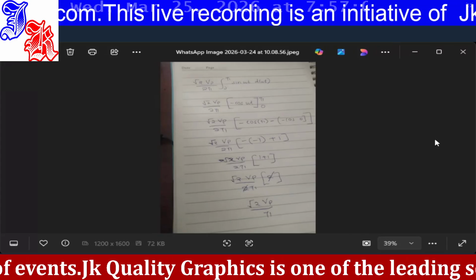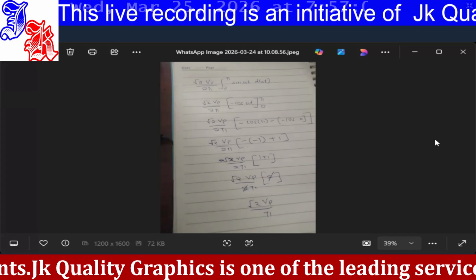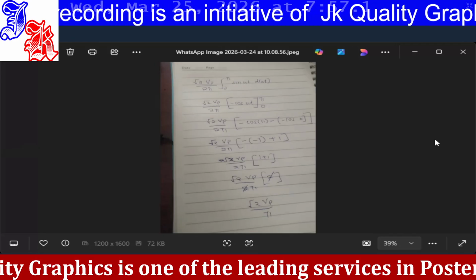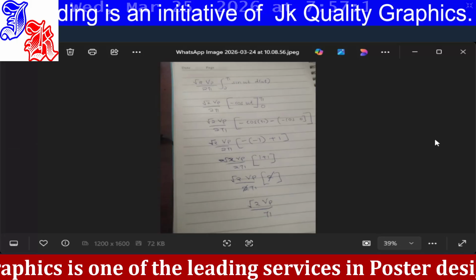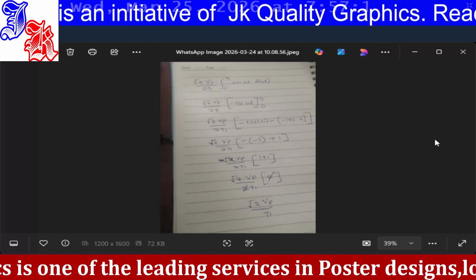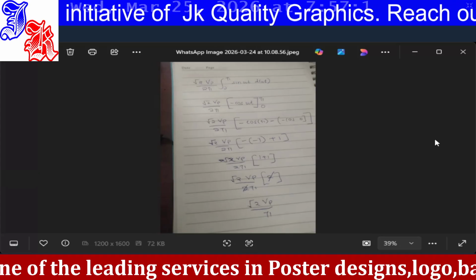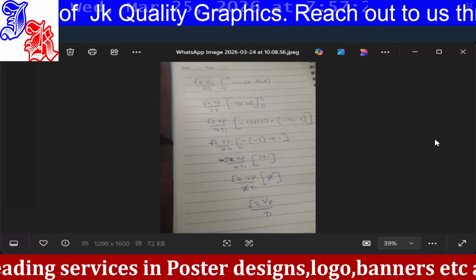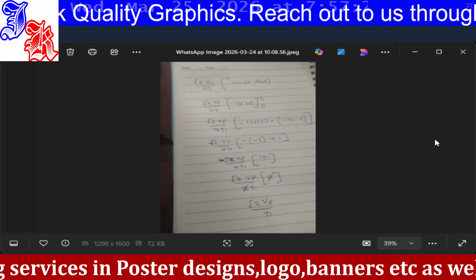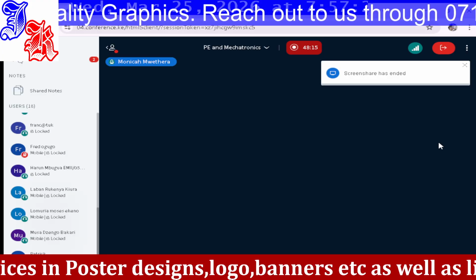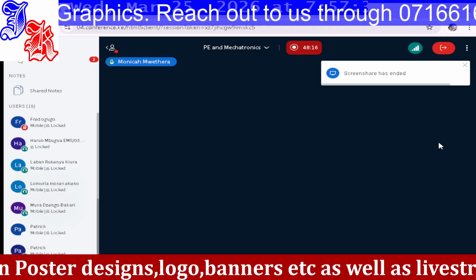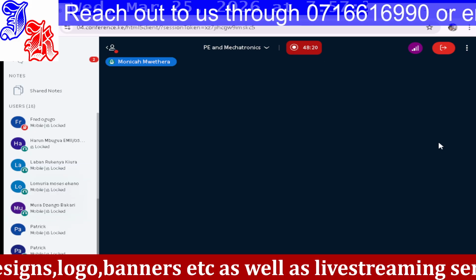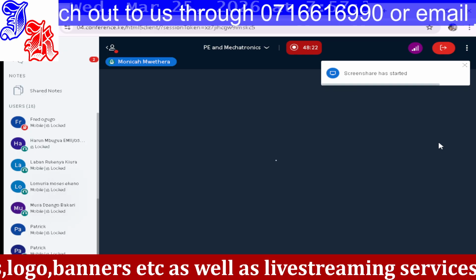So cos pi is -1, and then negative and negative becomes positive. Cos 0 again is 1. So this will be 1 plus 1. You have 2. Then the 2 will cancel with the other 2, and the final value will be root 2 Vp over pi, and that is what we had on the other side. So during the calculation, mostly this is expected to be shown when doing those calculations in your work. So that is when we have a single diode within a system.